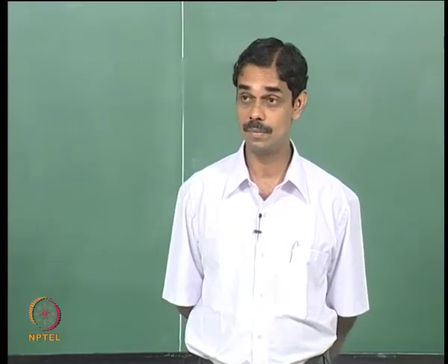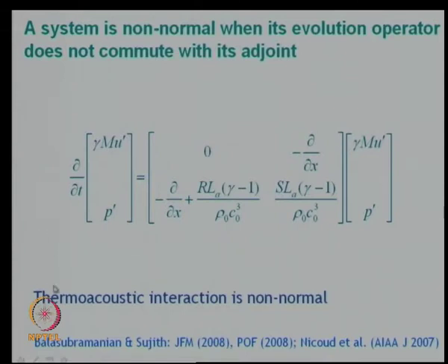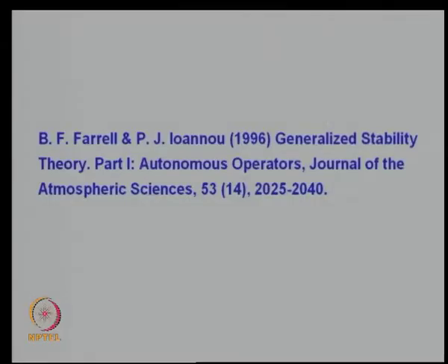Good morning everybody. Last class we looked at the non-normality of the thermoacoustic system. We found that this operator here is actually non-normal, which results in non-orthogonal eigenmodes.